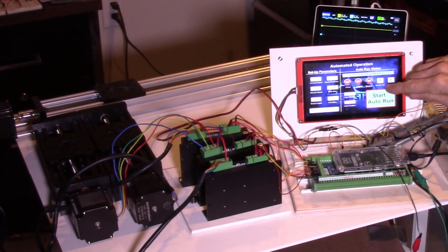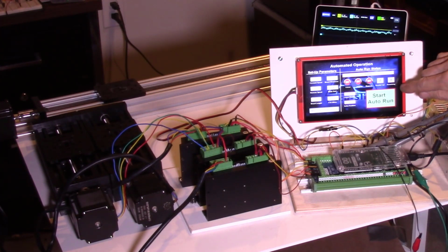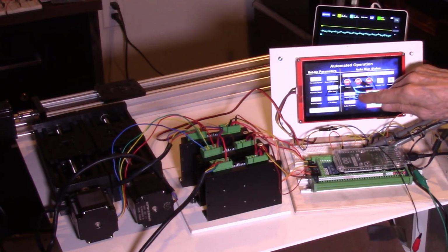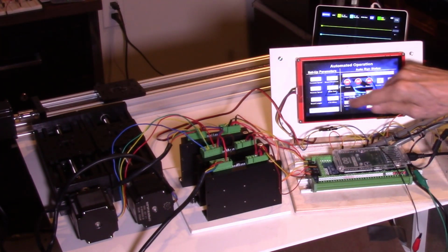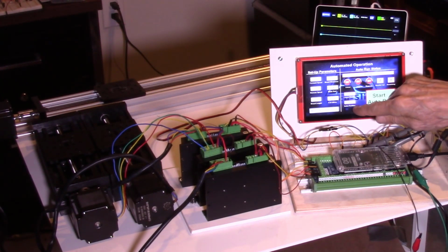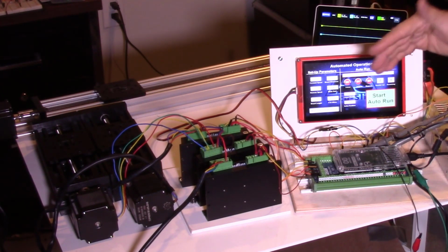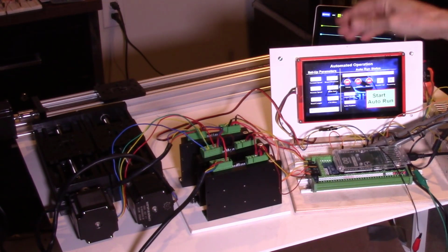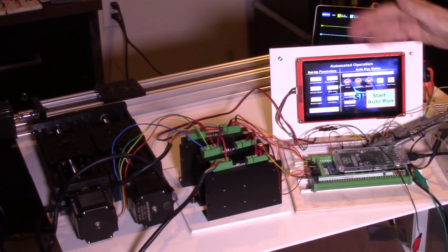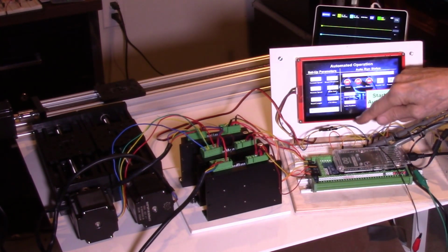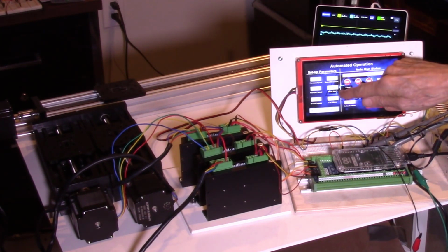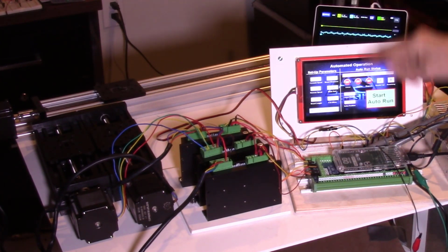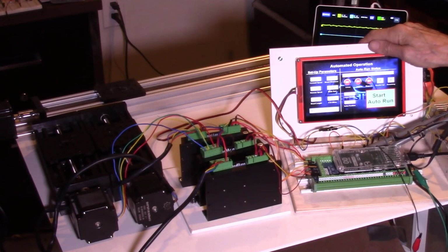And here it shows that it cut 2 boards, and there's 0 remaining. And the linear travel goes back to the 0 position, but my indexers actually moved in 290 thousandths of an inch for the first 2 boards. Each board went in 145 thousandths. 100 plus 45 is 145, times 2 gives me 290 thousandths.